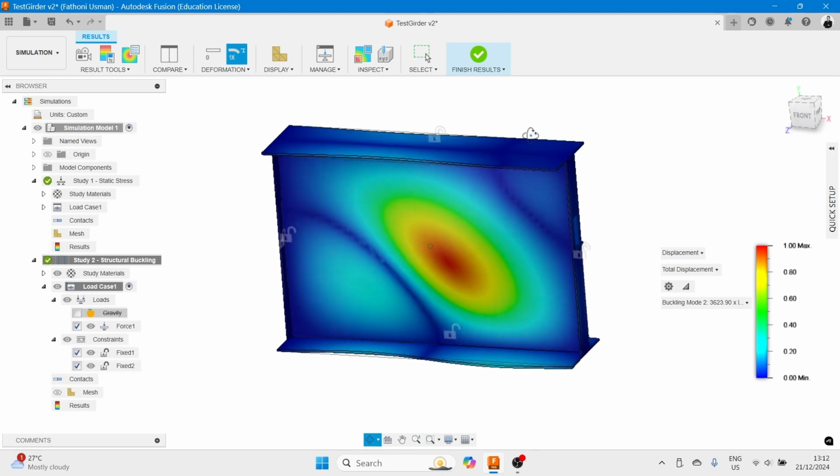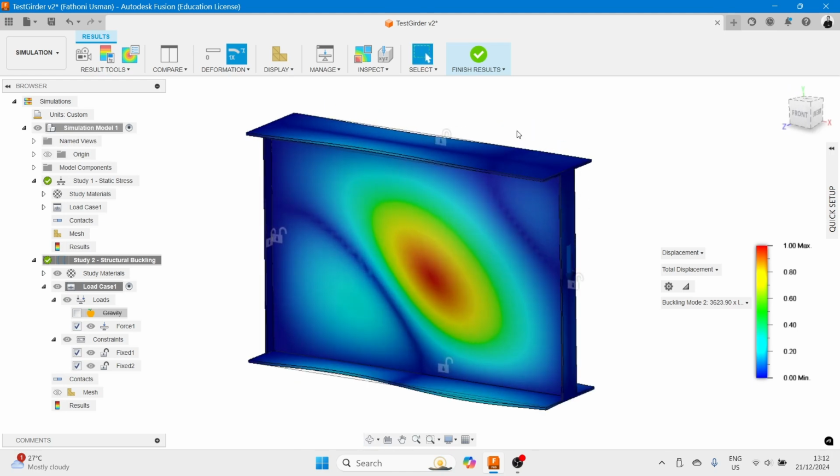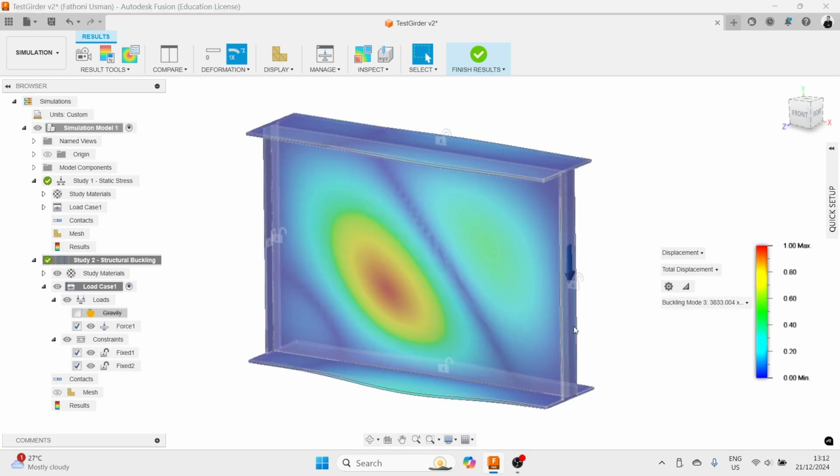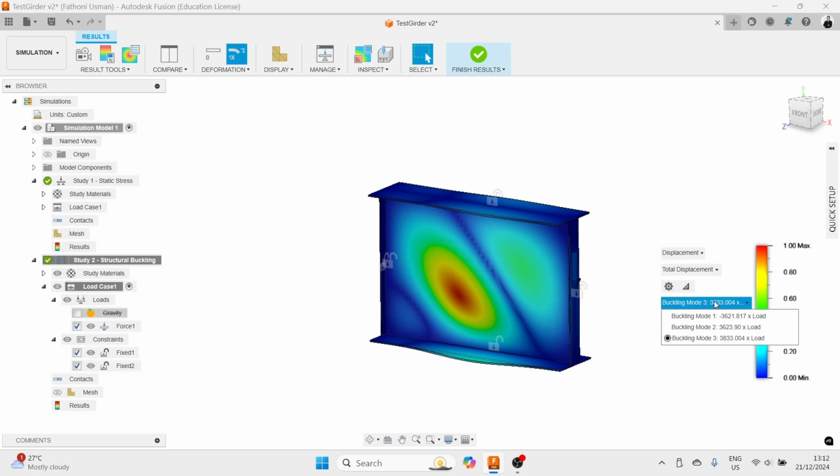So it's typical buckling. Save. And then the mode 3 is okay. So we have this one. So then, if you want to do the non-linear analysis, use buckling mode 1, which is sufficient because it's the smallest one.